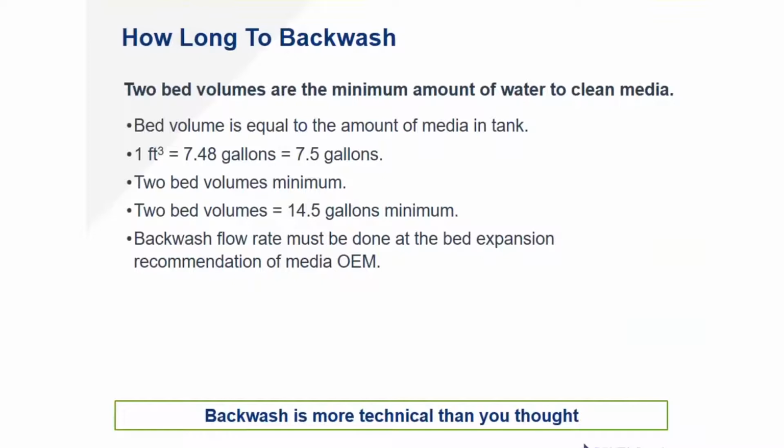The backwash flow rate must be done at the bed expansion recommendation of the media OEM. Backwash is a little more technical than we thought. We just thought we were running some water backwards through the filter to clean stuff up. It's critical to the life of your media.